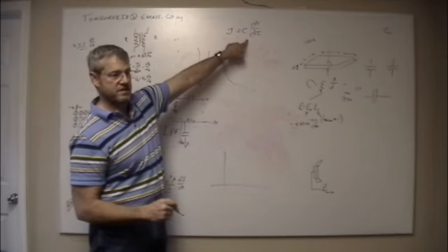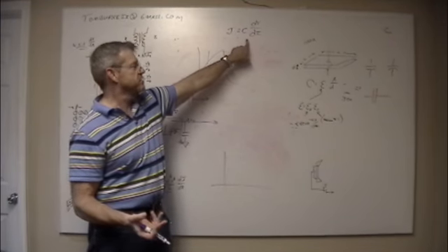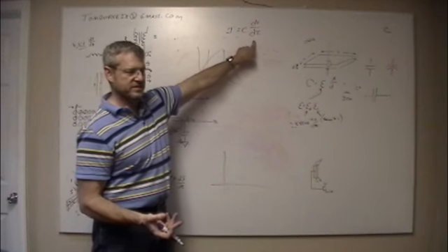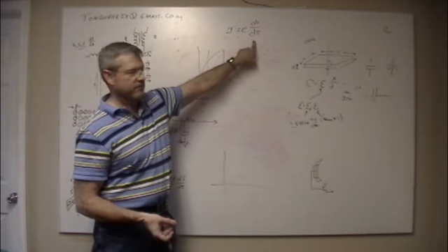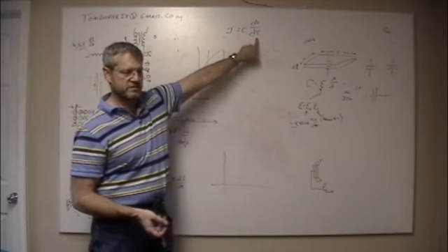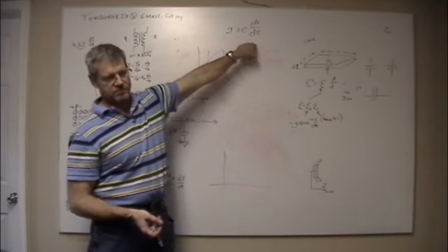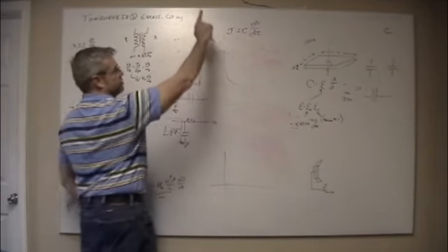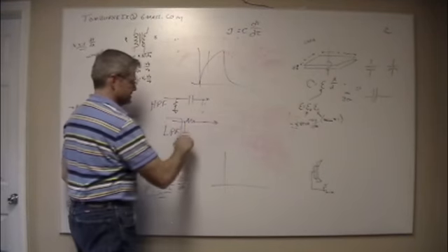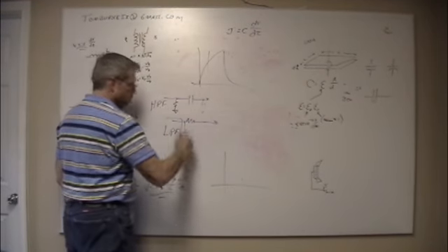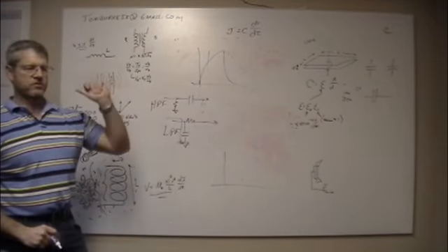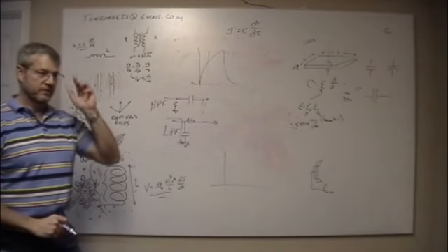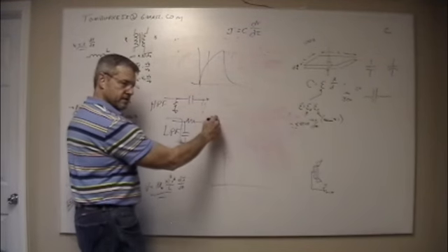Because C dV/dt, dV/dt is practically infinity. Because dt is so small, you know, if this is microseconds, that becomes millions. If it's picoseconds, that becomes billions. And so current shoots through the roof up to whatever this capacitance is. So wham! Everything that you can possibly source goes this way. And so nothing makes it past here.